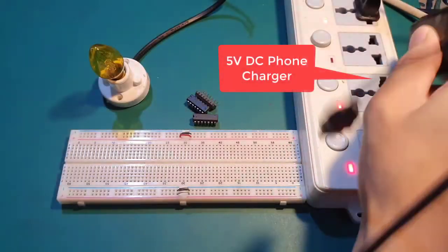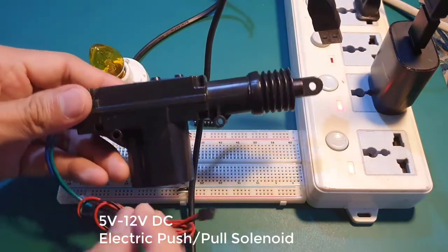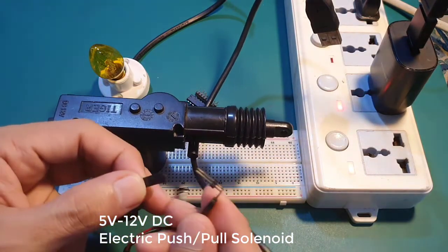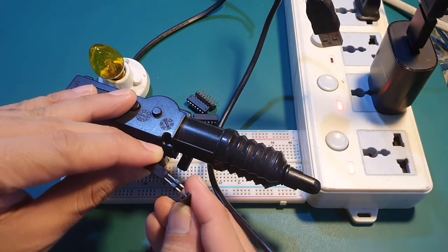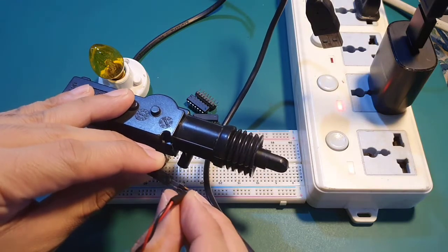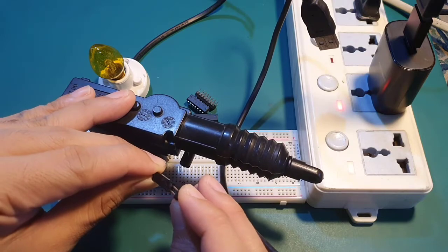And to simulate the door lock, I'll be using this 5 to 12-volt DC push-pull electric solenoid. This requires two wires to either push or pull anything depending on the polarity supplied to its two pins. So, in this instance, I'll be using two output variables X and Y to control the solenoid in both directions.